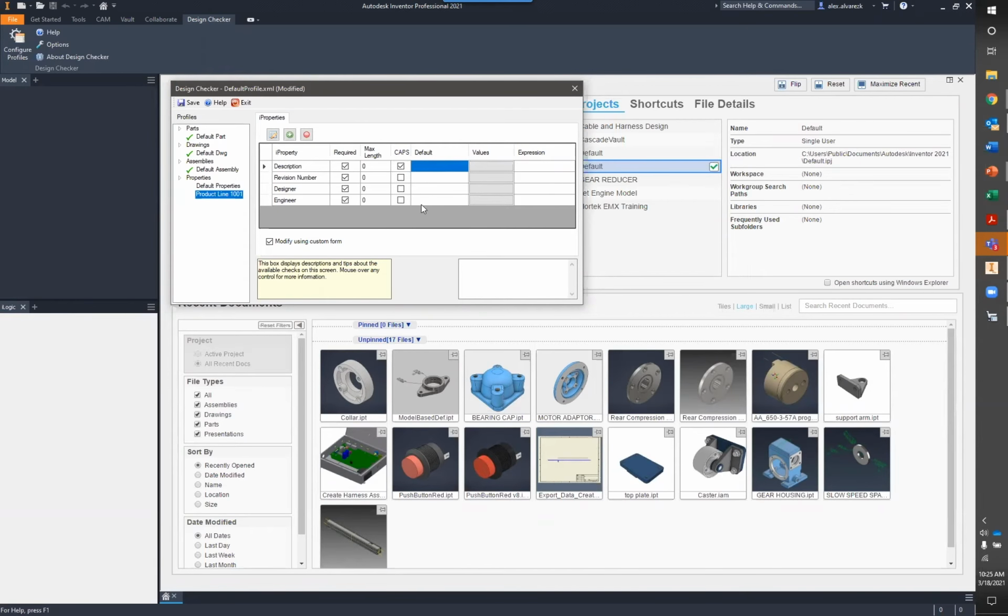Now, if you take a look at it, it's telling us that this hole right now, this counterbore, is going to be 0.134, or the through hole. If you take a look at your configured profiles, you guys can kind of see why, right? So we'll go into the machining tab, and it's telling you that the hole size increments are going to be 1/8 of an inch. Right now, again, that might not be feasible. It might be. I was talking to a customer a couple of days ago that they actually do have specific hole increments, and it really just depends on their product line.